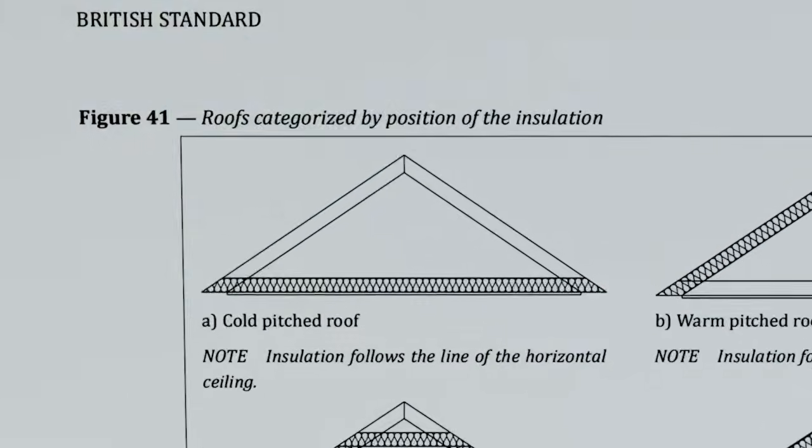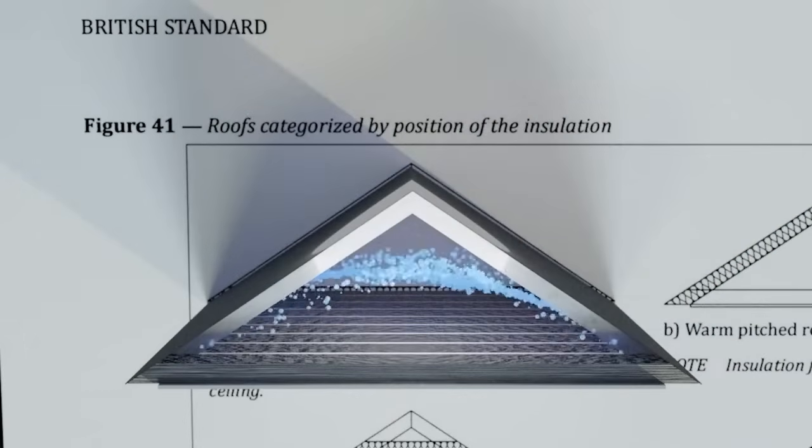For each of these roof types, the only prescriptive guidance in BS 5250 for removing moisture from internal sources is by means of providing ventilation. This means providing ventilation openings at the eaves and/or ridge of the roof, and using the resultant airflow to remove moisture. In a cold roof, this means that air must circulate through the large loft void to remove warm, moisture-laden air and prevent condensation occurring on the colder surface of the underlay and roof timbers.